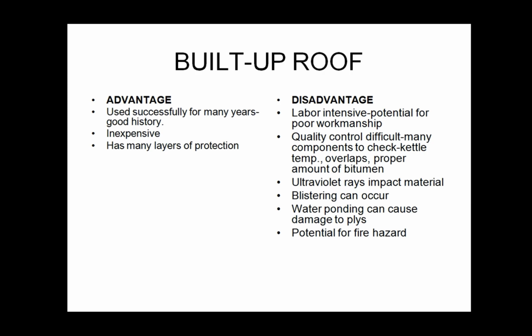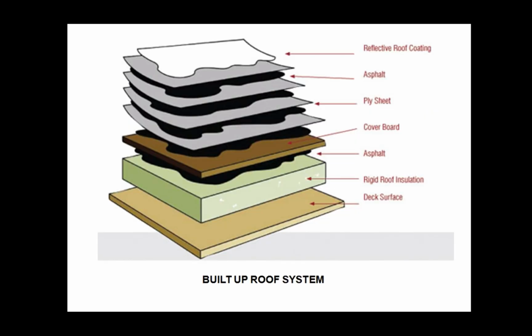And sometimes this material doesn't have as good a fire retardant rating as other materials and other roof designs. Mainly because you have all these plies of material and tar or asphalt in between, so you do have poor fire protection ratings with this material.